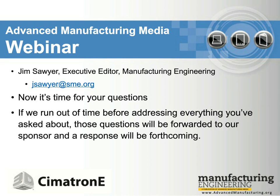That would be considered 3+1 or 3+2 machining usually. And yeah, we don't charge extra for that type of programming. Well, if you wanted 4-axis simultaneous or 5-axis simultaneous, then that would be additional software. But that would just require a custom post. So either a 4-axis or a 5-axis post would handle all of that.